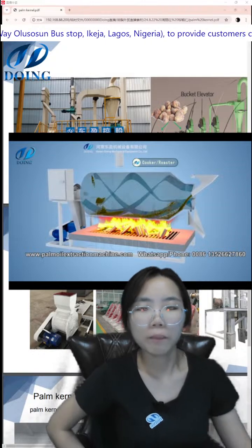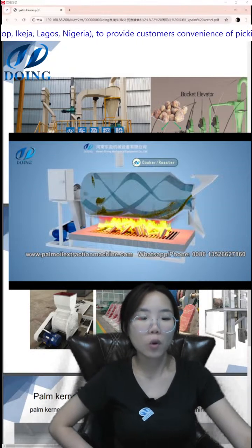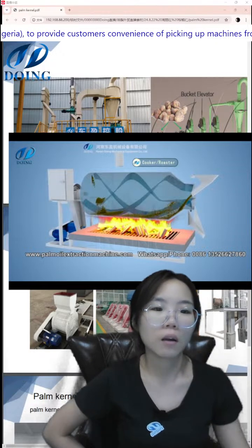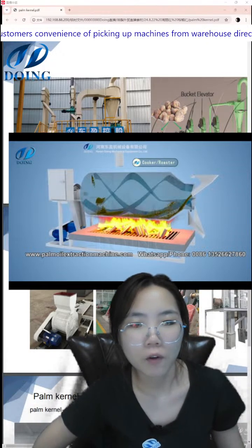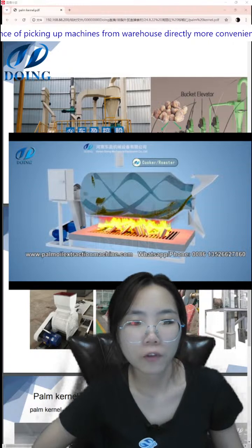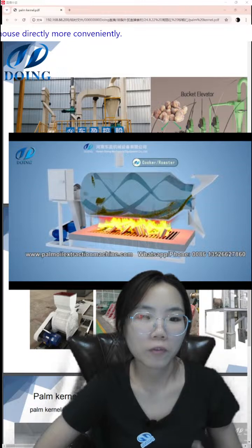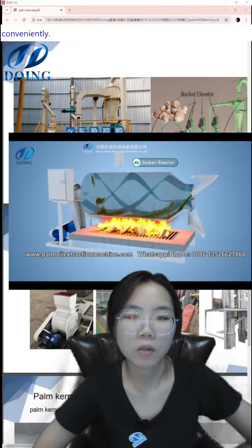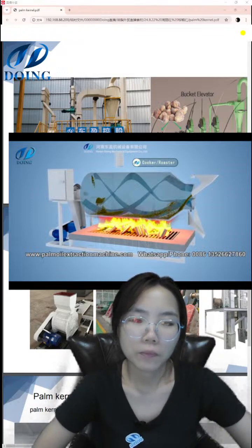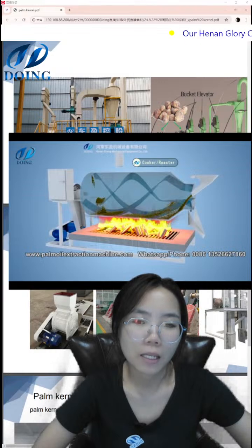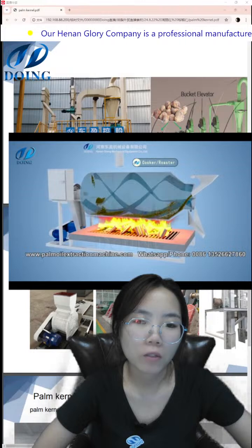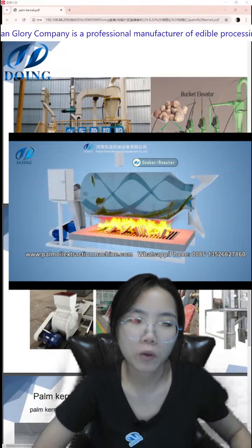If this is the cooker, if the raw material is too dry, a certain amount of water needs to be added for the roasting. The water level before entering the press needs to reach about 10% to achieve the best pressing. The cooker is a steam cooker.